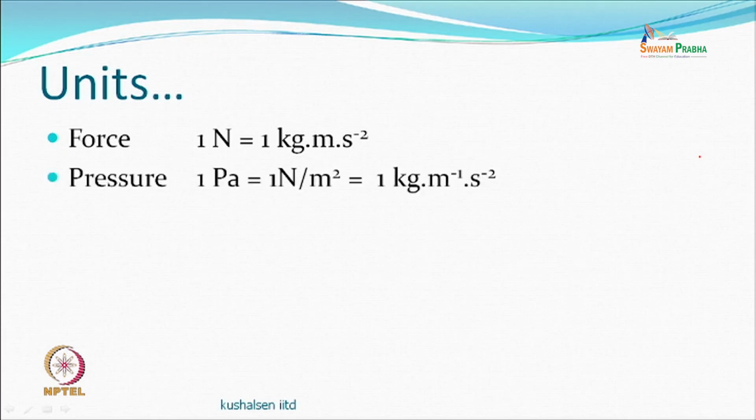Just so that we don't get confused in case some small numerical comes, you have force defined as a Newton, all right. This is kg meter per second square, because this is mass into acceleration. Then you have pressure, which is in Pascals, the Newton per meter square. There also we use, just before, a term like this, Pascal second, which became the viscosity.